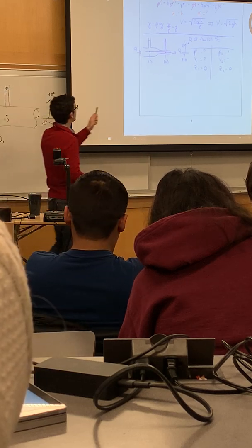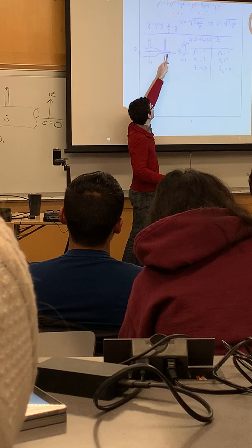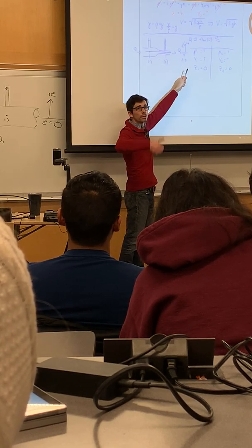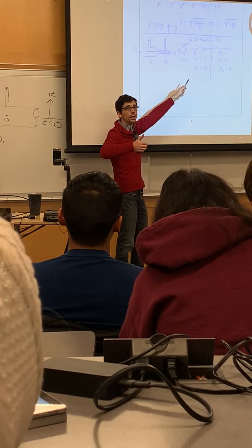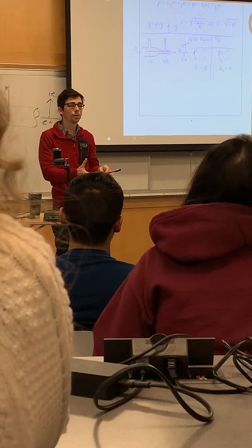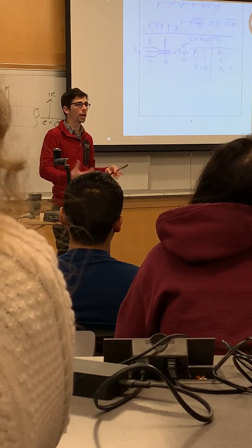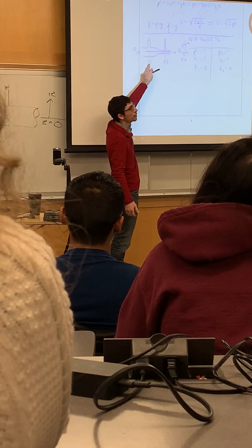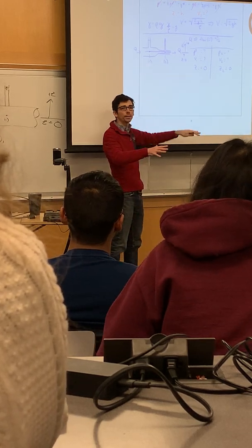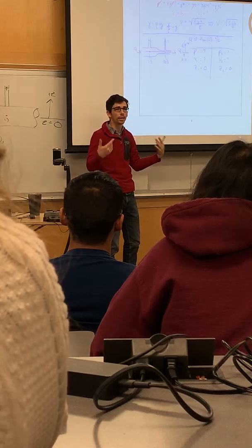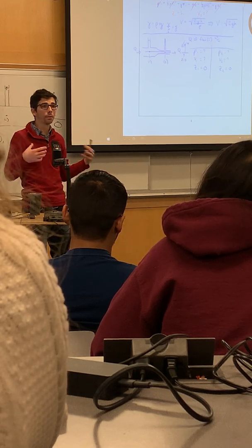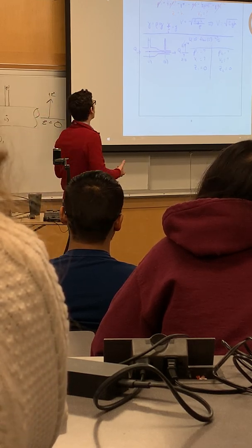The only way to move the same amount of flow through the part downstream of the constriction is to increase the velocity, right? And the energy to make that change in velocity has to come from somewhere, and it comes from the static pressure embodied in the fluid at point 1. So what's happening here is, we're getting a little bit ahead of ourselves, but these are great questions, because these are the sort of thought exercises that will make the application of the Bernoulli equation a lot simpler if you physically understand what we're talking about.